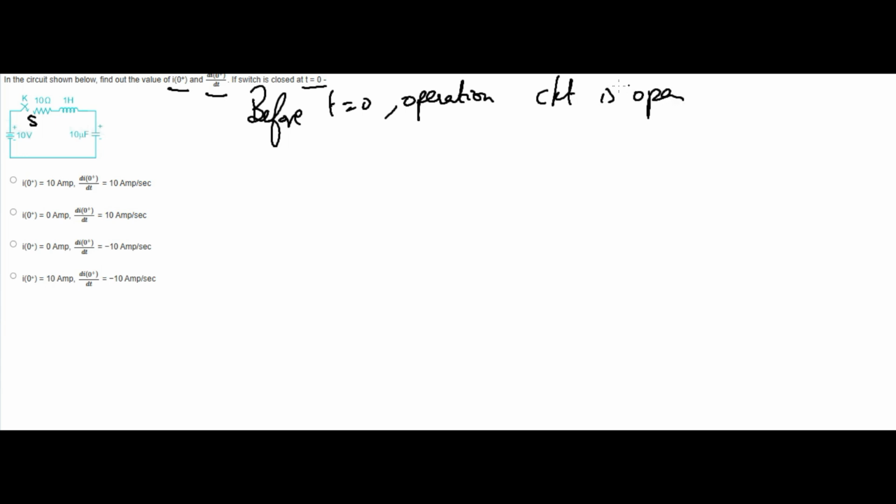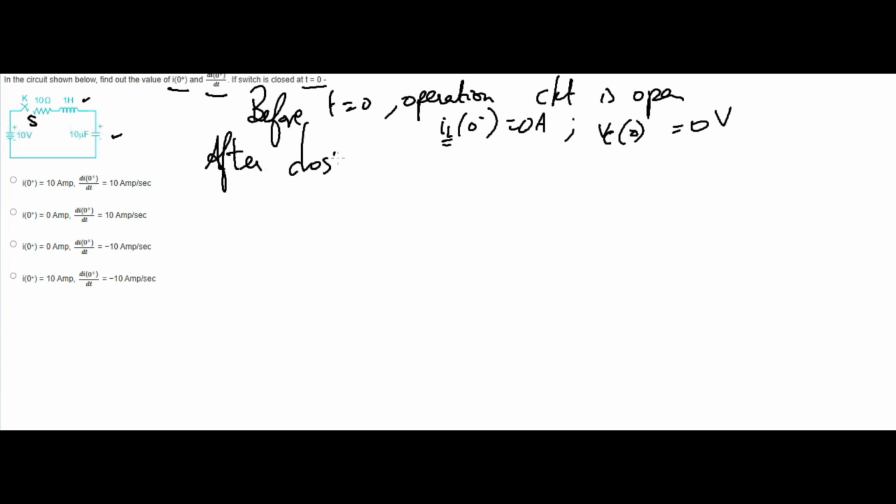So the IL of 0 minus is equal to 0 amps, and the voltage VC of 0 minus is also 0. IL means through the inductor the current is 0, and through the capacitor the voltage is 0, because the inductor corresponds to current and the capacitor corresponds to voltage. Now, after closing the switch...